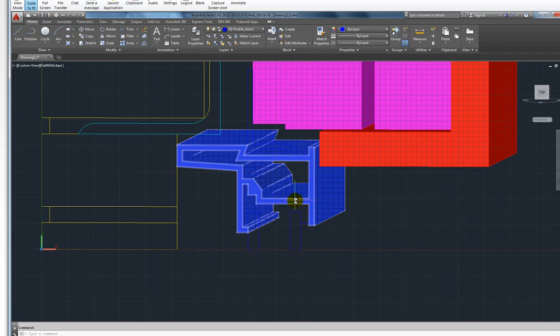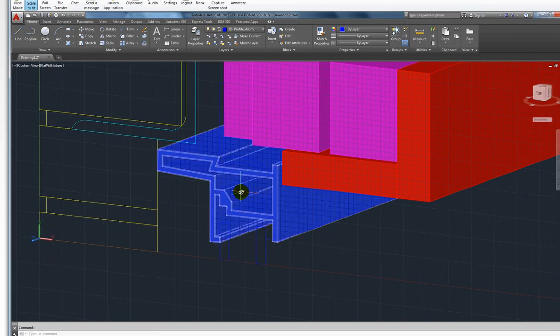Okay. Overkill gets lines that are, if you have double lines, you don't want them. If there's 2 lines that sit in the same position, because you drew like this for like an hour, because you were watching Seinfeld in the background and didn't realize it, you can kill them all. Okay? And you get 1. But they have to sit in the exactly same position. If they're slightly off, it assumes you want that. If they're 2 closed P lines that do this, it won't do anything. It's just when you have open lines. Overkill will be an important thing. So you saw that? Okay.